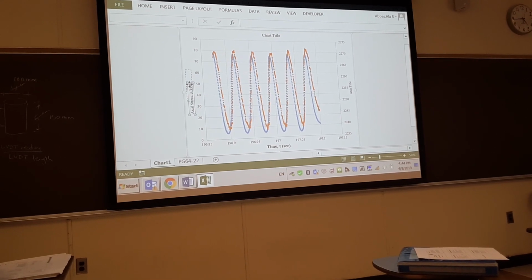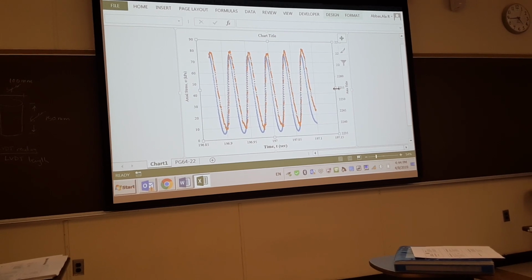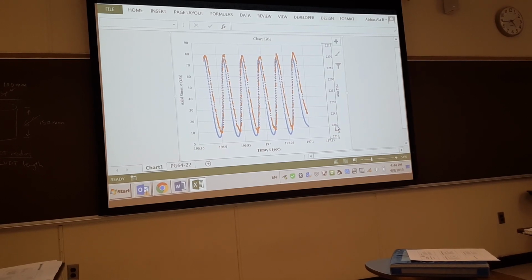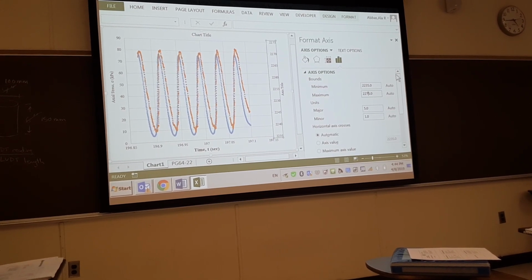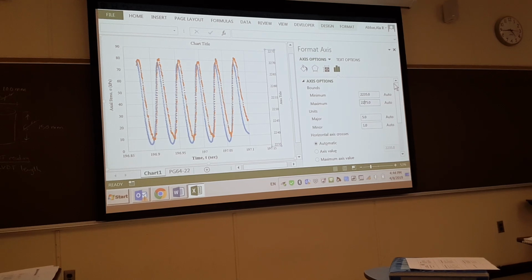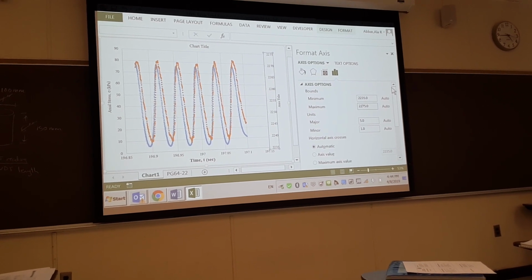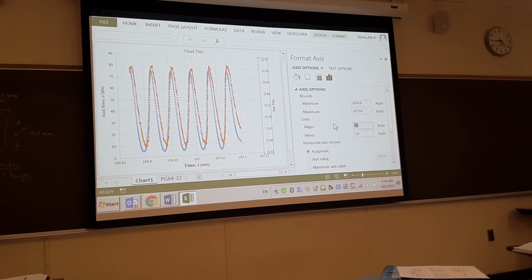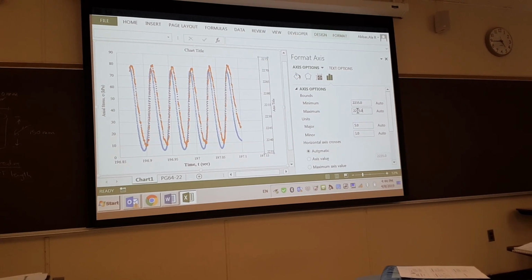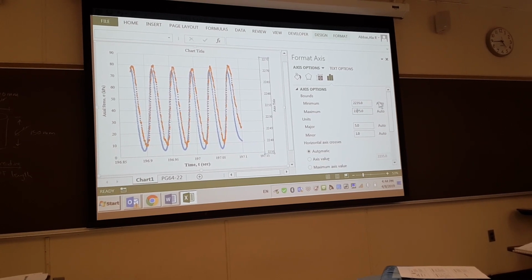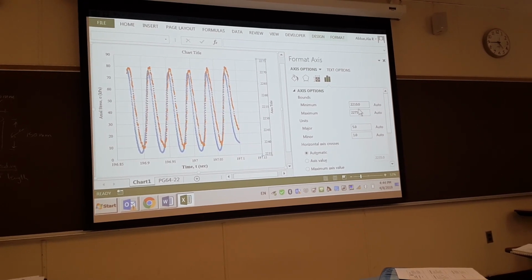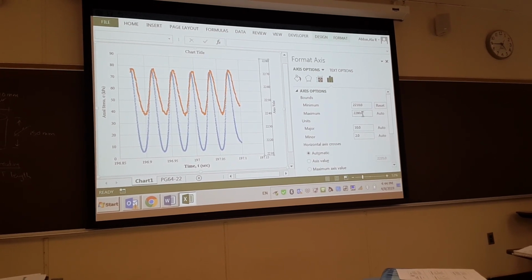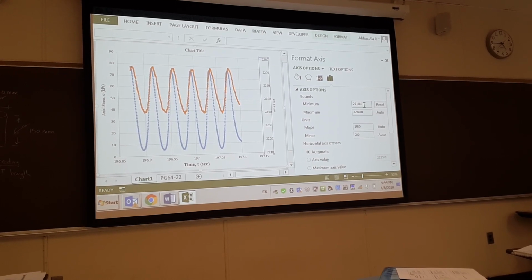And this is your axial strain. To make things align better, I'm going to change the axis for this so that they are both aligned. Maybe I can make this 235. I have 90, so I'm just going to make it maybe 4.5 in here. This is going to remain. So I'm going to make it 70. I'm going to make it 10 maybe, then 80. You can do any scale you want really, as long as it's consistent.